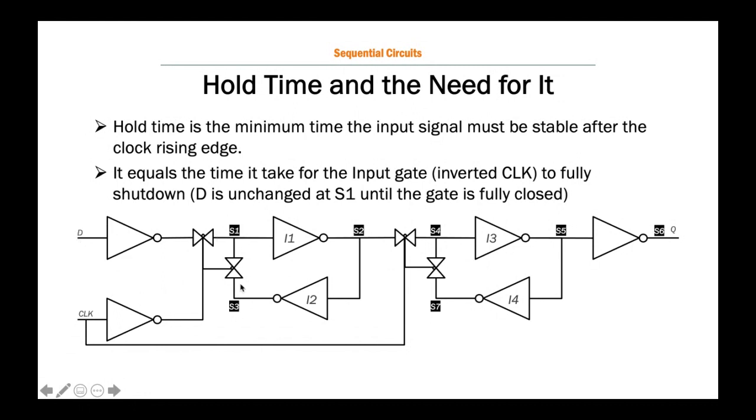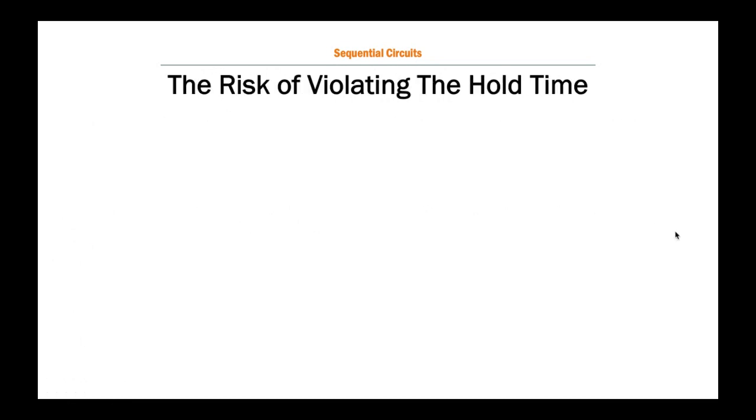You had the stable, desired value coming in, all of that's fine, but still the gate did not fully close, which could risk that an undesired value comes through, some contamination delay, a random signal that quickly passes through the gate, and since this is open, that value is going to loop and come into that memory state and change the value of Q. This is the risk that we're looking for.